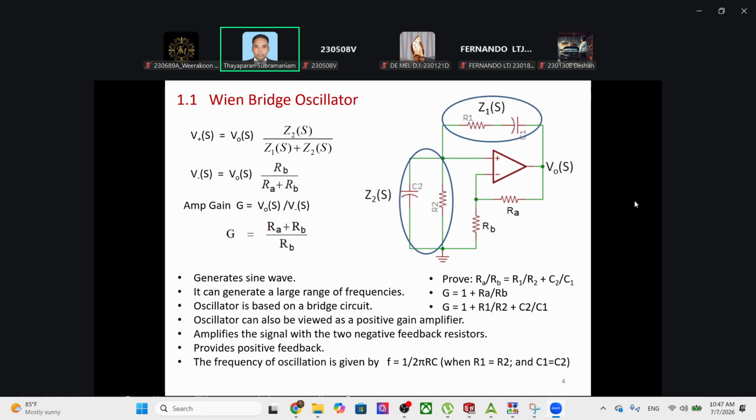So not only that, if you want to increase the maximum frequency, we have to make sure that these two input currents are as small as possible. Instead of 2 microamp, you can go down to 1 or 2 nanoamp. Then you can bring the path current to around 0.1 milliamp, 100 microamp here, and that will oscillate fast. Remember, capacitance has to be reduced, resistance has to be reduced in the positive feedback.